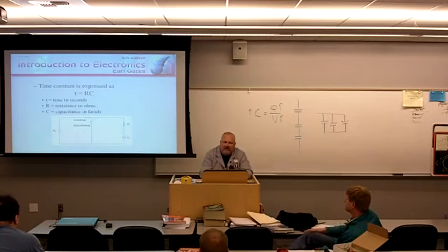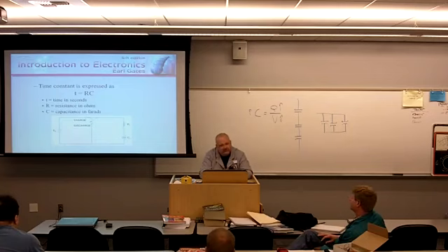And physically what's happening with this, what kind of a circuit is this? Series. Series RC circuit. And when I close this switch, this capacitor here is going to be at 0 volts and it's going to start charging up to 100%. How long is it going to take to get to 100%? 5 time constants. How do I figure out what 1 time constant is equal to? T is equal to R times C.